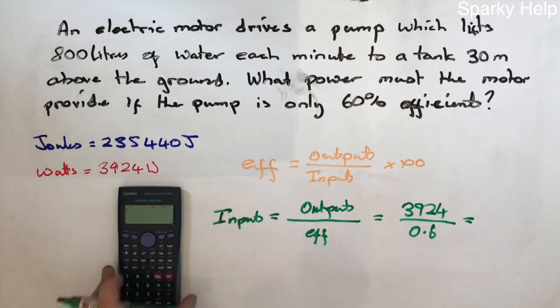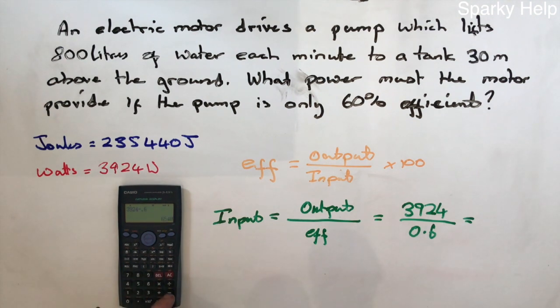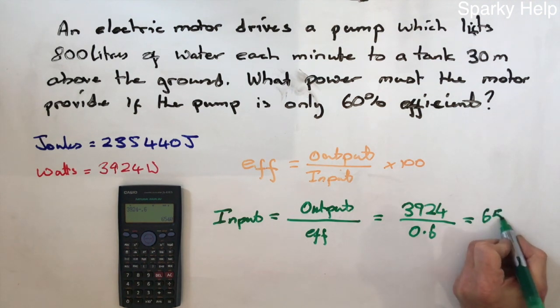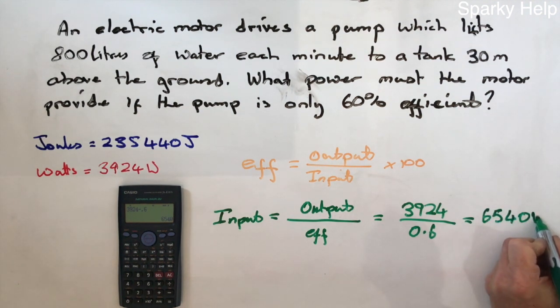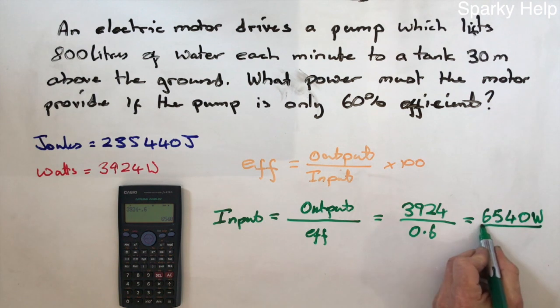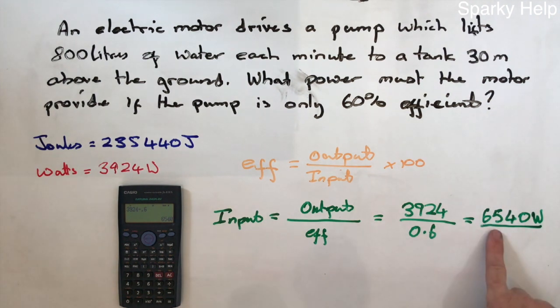If you do that calculation, that's 6540. So our motor would require basically a 6.5 kilowatt motor, or the next size up, to work this.